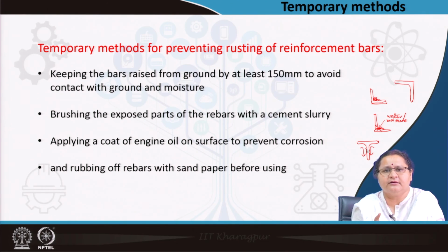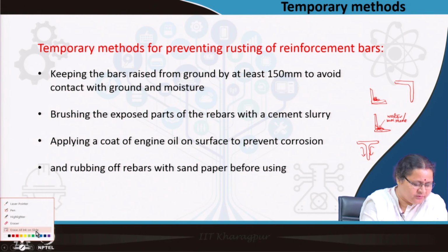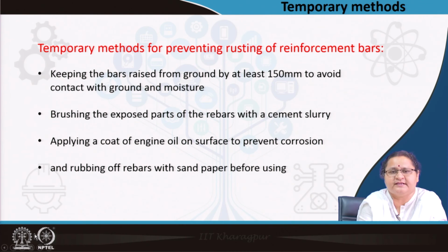So, a clear instruction should be that these sections should be placed in such a way that water accumulation is not possible. Even dust accumulation is to be avoided. We have to be very particular on this point of corrosion. If we can actually check the corrosion, then we can do good justice to the use of steel in the building industry.